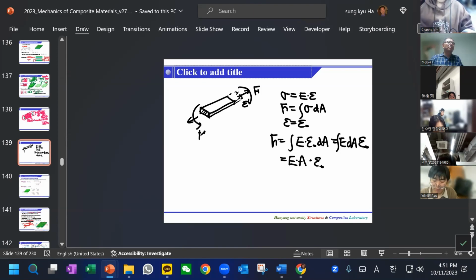Okay. And another point here is that we have a bending, like this much bending, and the moment. If we have a bending, this will deform like this, and this will have a radius R, and this will be the curvature. So by definition, the moment will be the stress times the through thickness and dA, right?